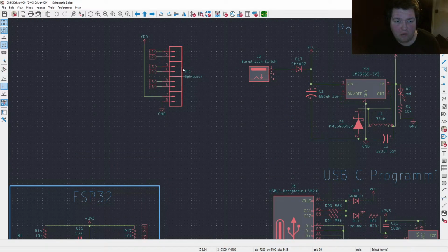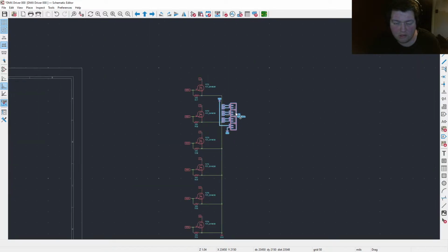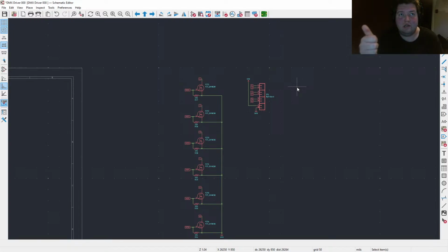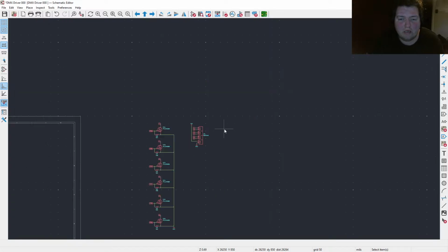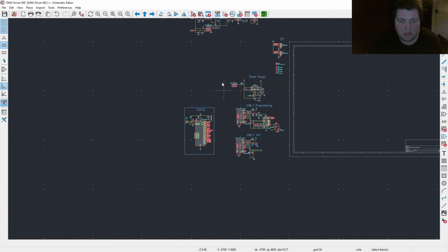We have power for external lights that I can control from DMX. This board's gonna act as like a 3-in-1, so I can use it as an HID input device over Wi-Fi, which is one of my intended uses. Hence the dual USB ports.